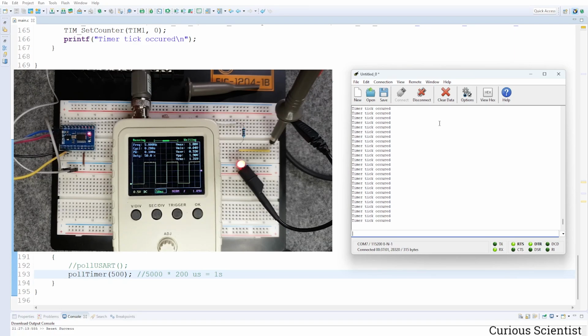And that is very good, because it's not blocking the rest of the CPU. So you can do other stuff between 2 blinks, or between 2 sensor readings, and so on, without actually blocking the code. Because when you apply the delay, then the code is not doing anything else. It's just waiting in that specific line.